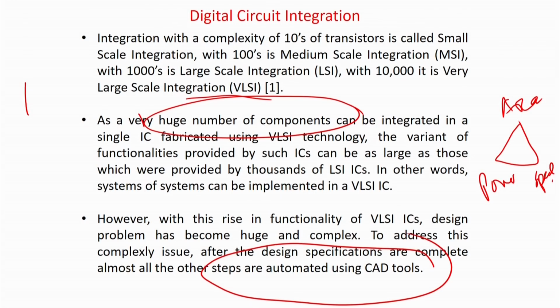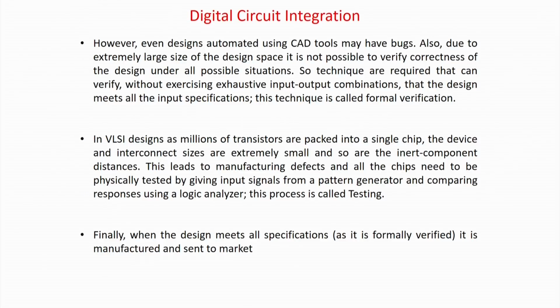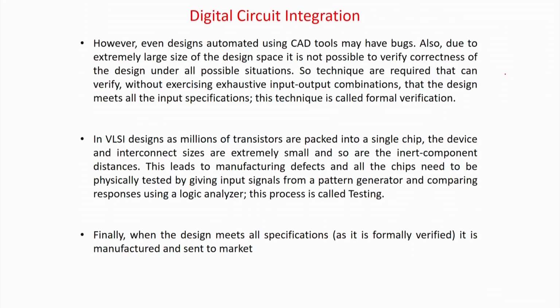Anyway, let us go ahead. Say for example you are a very intelligent engineer, you have given very nice block level diagrams and your CAD tool is also very much optimized. So you get a very nice circuit with low area, low power and high speed in a very quick processing time, because everything is optimized, input and also the CAD tool flow. But again, how do you know the design is correct, whatever you intended? Because you will give inputs in some high level language like SystemC or SystemVerilog, and finally you are going to get a physical layout, that is the transistors. How do you know that from system specification to layout, all the things are equivalently translated or not?